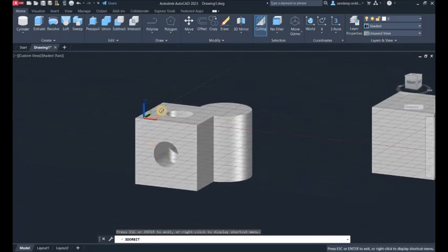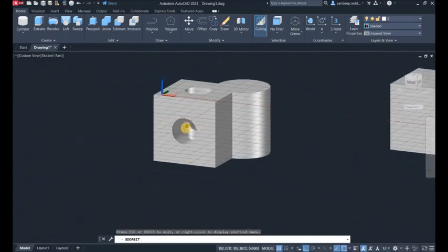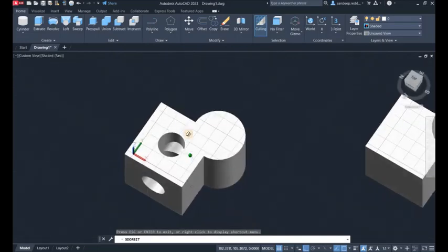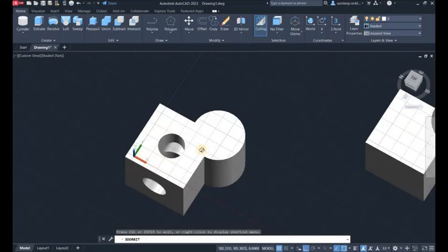So in order to draw the two cylinders respectively, for the horizontal cylinder, I made sure that this particular face was my UCS, parallel to the XY plane, sorry. And just as I showed you a while ago, the XY plane here is parallel to the top surface, so I draw my 2D object and then extrude that along the Z-axis. And with that we complete the lab 4 coverage.